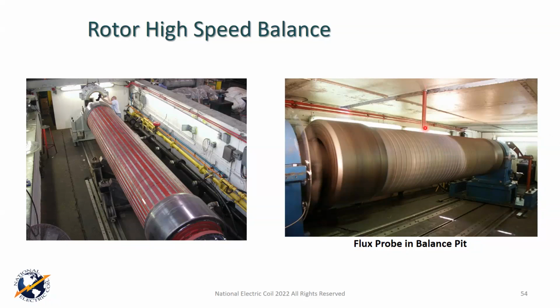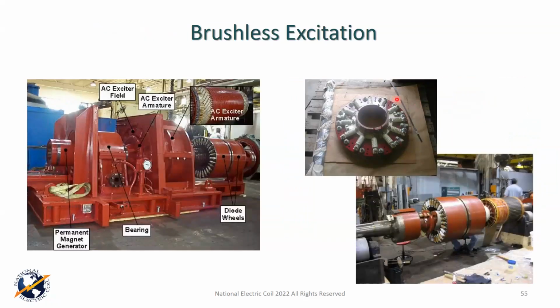I have people tell me all the time, well, I want to run a flux probe to see if my rotor's grounded. It doesn't do anything but look at turn insulation and look for turn shorts inside your rotor winding. That's all it does. So that's basically the rotor aspect, but I wanted to touch on brushless exciters because a